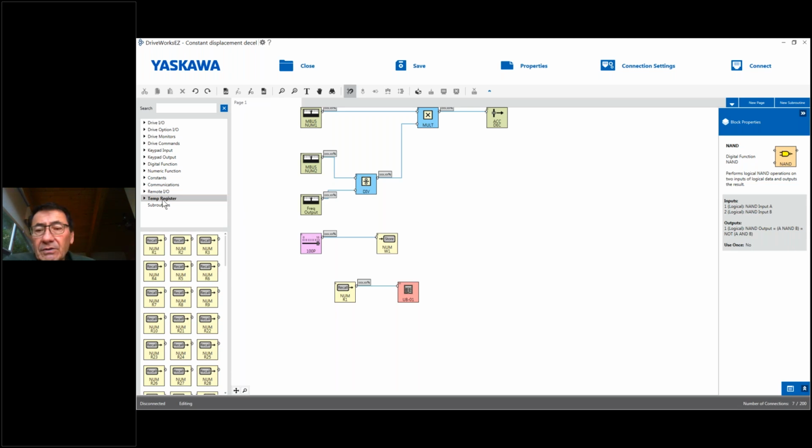So, for example, vel ratio. I'd probably store it in a temp register and then call it up and use it in a formula. The temp register will be updated as we're running along the conveyor so that the number will always be available to me, and therefore will be available to me when I hit the prox, and I'm going to need it to designate the new decel value in C104.